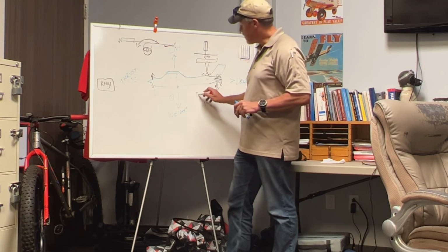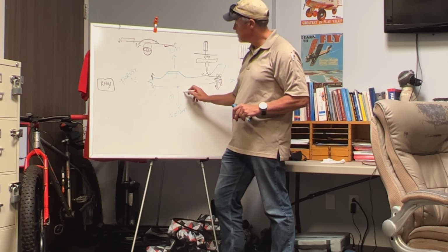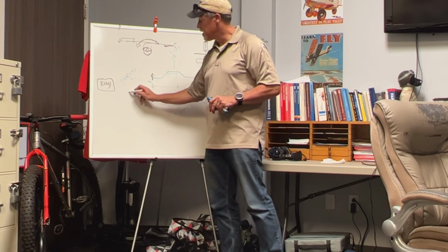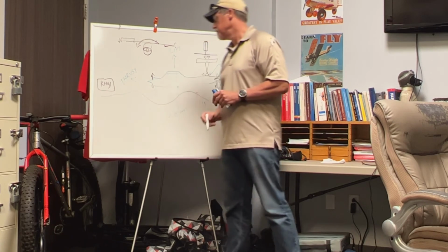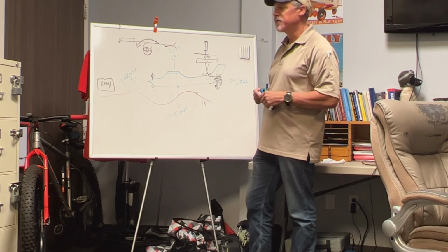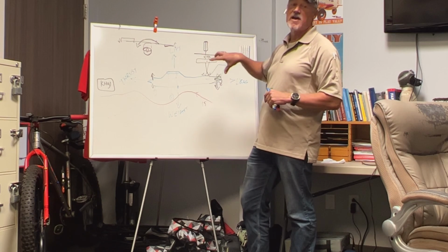And you're going to notice the airplane's going to pitch up and it's going to start slowing down. As it slows down, it's going to pitch back down a little bit, and the airplane's just going to kind of go through a couple oscillations, and eventually it'll level back out on its own. So that's the stability that's built into the airplane. And we'll talk about stability and dynamic stability as it pertains to the design of this particular airplane.